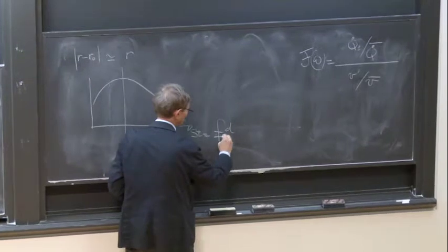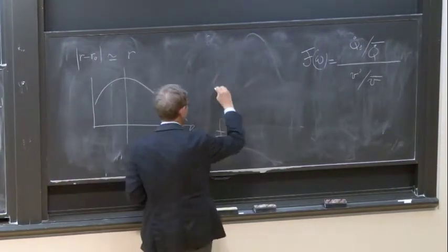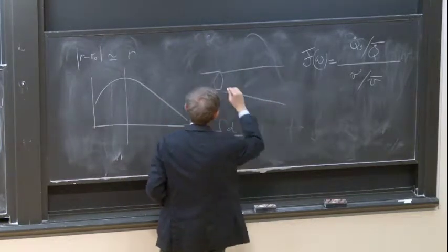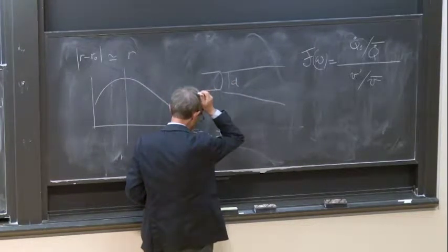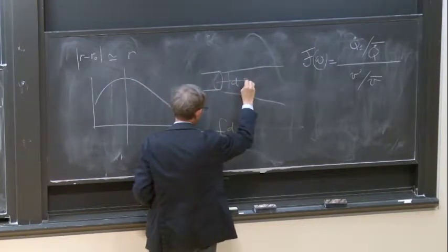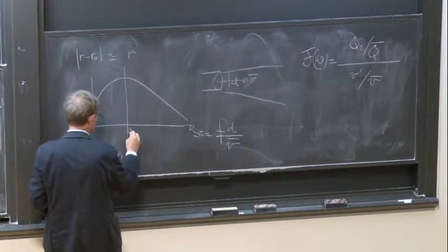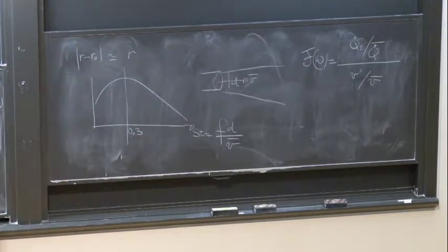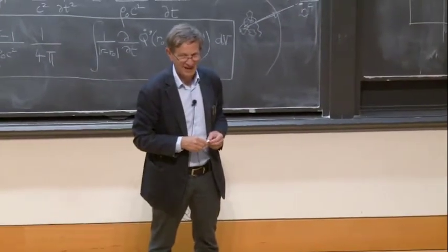d over the velocity. So for example, you have a jet coming out from this nozzle here. This is the diameter. So you multiply the frequency by the diameter and divide by the mean velocity here. And typically the jet noise is maximum at Strouhal number of 0.3. So now that's in subsonic. Okay. Supersonic, is the Strouhal number different?